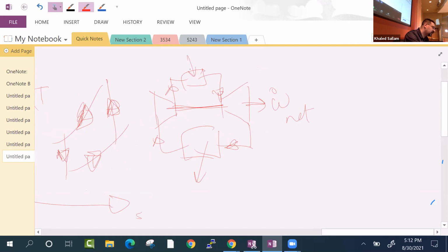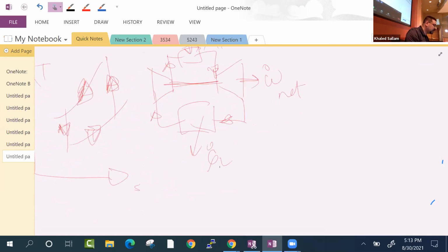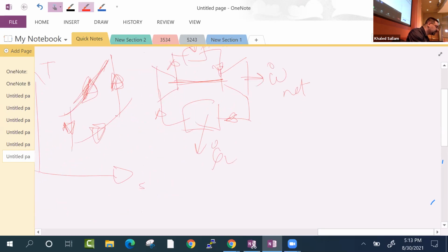So you give it Q dot H, and you lose some Q dot L, and you get work from the turbine, of course the compressor takes work, but the work is smaller than work net. This is a very old cycle. They had this on paper forever, but they just couldn't make a compressor that takes less work than the turbine and runs on the same pressure until the Second World War and Germans started having those jet engines, right?